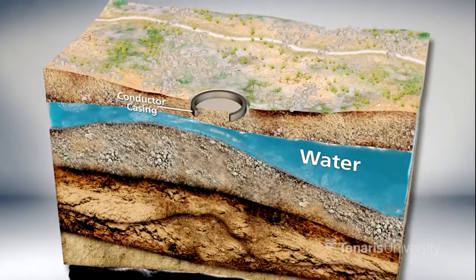This is required to circulate the drilling fluid up to the surface without eroding the upper sediments below the rig foundations. Generally, this is a very short string, normally consisting of 1 to 3 joints, and as the loads at the surface are not severe, any pipe can eventually be used for this application. There is no need to make a specific design for it. This conductor can be driven by a pile driver, that is hammering, or simply running and cementing after that section of the hole has been drilled.